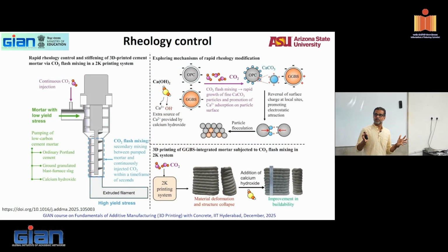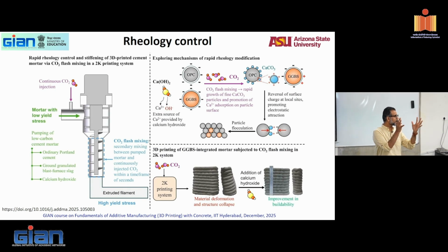So we will continue with the idea of rheology and rheological modification. So a few things, right? We ended last session with the idea that yes, you can do all the rheological tests. You typically will do the tests on pastes. And when you have to do concretes or when you have to actually print, the printer also becomes part of the problem or the solution. So you have the mix that you have tested, you print it, and you evaluate what the correspondence are with the properties and the printing.